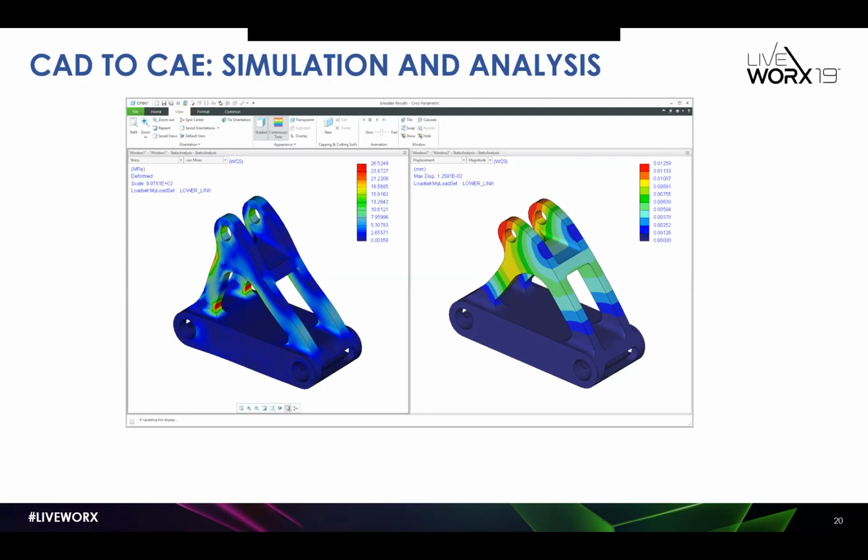In this way, empowering designers with analysis tools allows them to perform trade studies on their design concepts and select the best one, and then make it better. Once someone becomes comfortable with modal, you can quickly and easily progress to linear static analysis. You teach the designer the right way to apply loads and constraints, how to simplify design models, and they're on their way. Static analysis will allow them to size their parts properly, figuring out wall thicknesses, hole and shaft diameters, and where they need fillets.